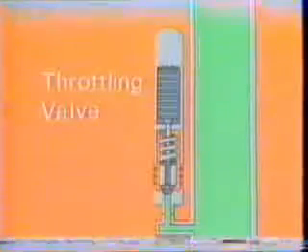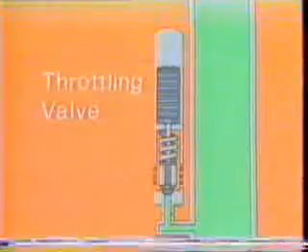If the tubing pressure is less than the casing pressure, it is possible for the throttling valve to close even before the casing pressure has dropped to the dome pressure. In fact, a throttling valve will close with a reduction in tubing pressure even though the casing pressure is held constant. This type of valve then requires a buildup in tubing or casing pressure to open and a reduction in tubing or casing pressure to close.